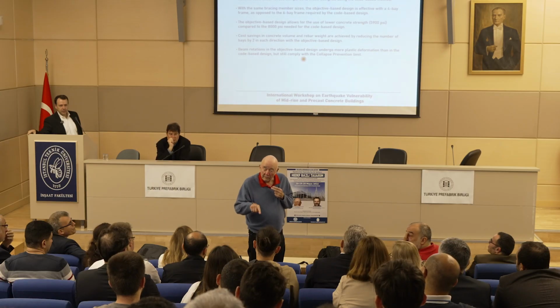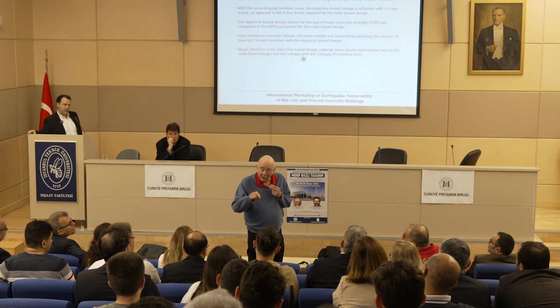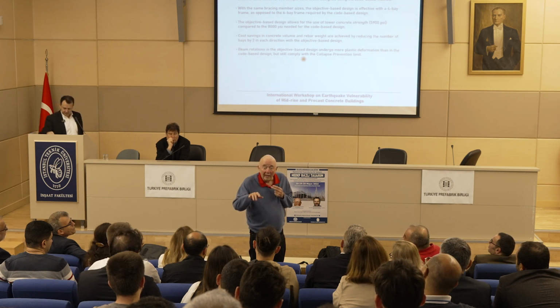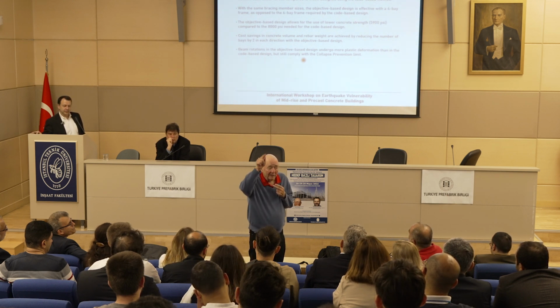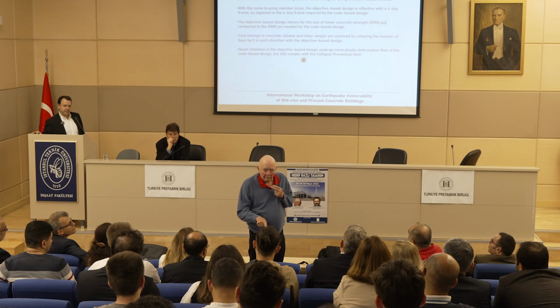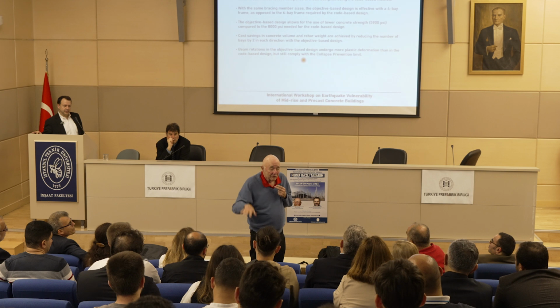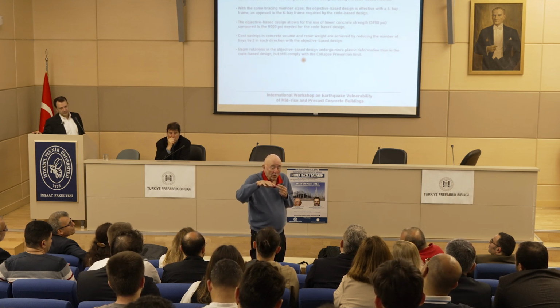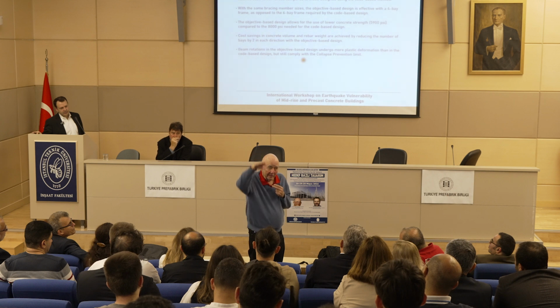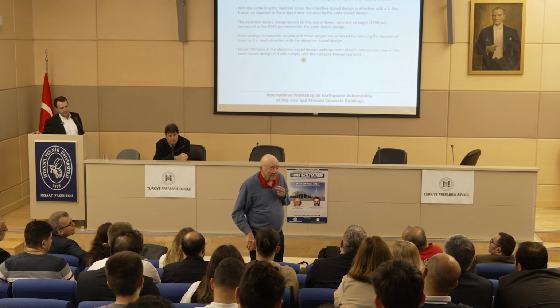As I showed you in the Northridge earthquake, the vertical wave demolished the system before the horizontal wave came. And as you can see, the columns were still standing. The vertical load carrying system was not reinforced to take the up and down motion.